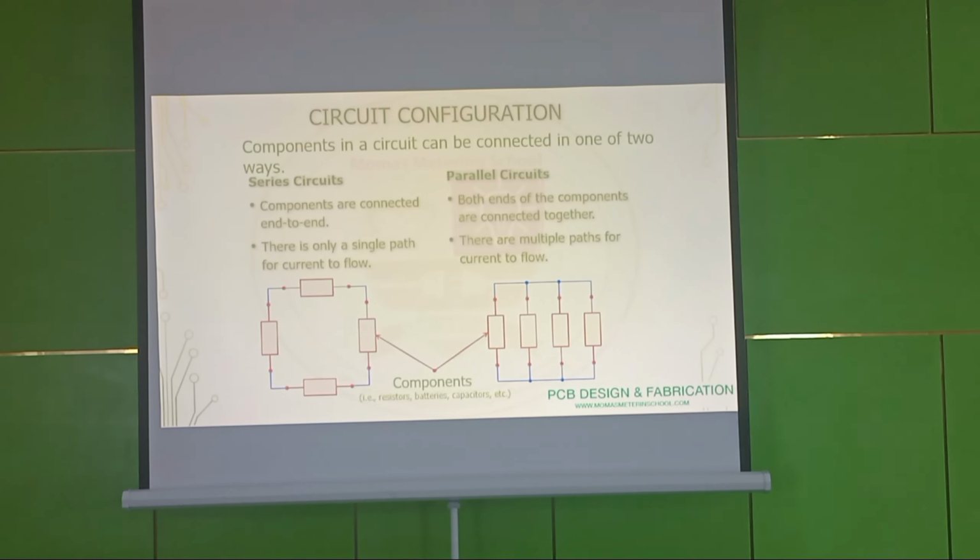I know if I see a resistor in series, I know that okay, there will be voltage drop across each resistor. And the voltage drop across each resistor will be proportional to the resistance of the resistor. That's it. And you know what happens when you have a voltage, the same current flows through it. If it is in series, or if it is in parallel, the same voltage across all resistors, but different current flowing through each resistor. And the current flowing through each resistor depends on the resistance value of the resistors.